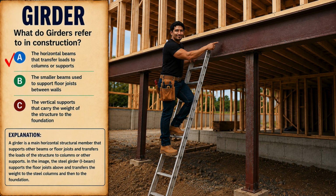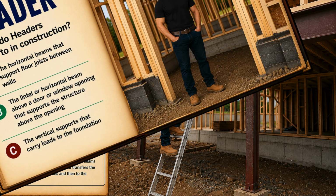The answer is A, the horizontal beams that transfer loads to columns or supports. A girder is a main horizontal structure member that supports other beams or floor joists and transfers the loads of the structure to columns or other supports. In the image, the steel girder, the I-beam, supports the floor joist above and transfers the weight to the steel columns and then to the foundation.